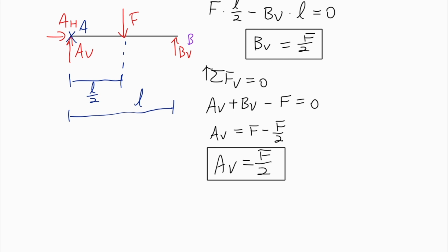Please remember to always choose an equilibrium condition that gives you only one unknown. Taking a condition that doesn't give you an answer wouldn't make too much sense. Make sure your equation only has one unknown, and then you can set up any equation you want. As I mentioned earlier, forces need to cross a lever arm to induce a moment.